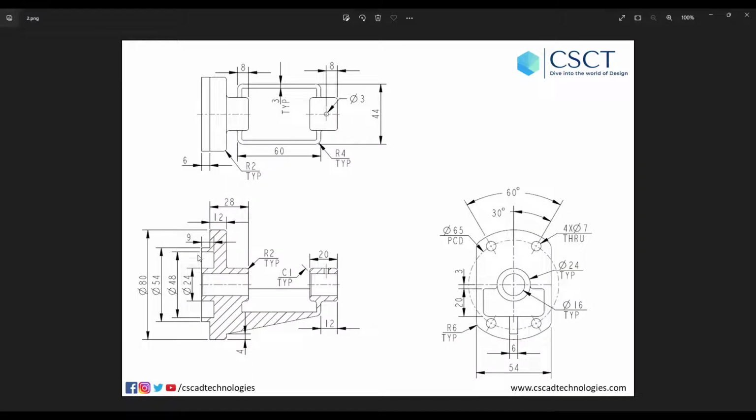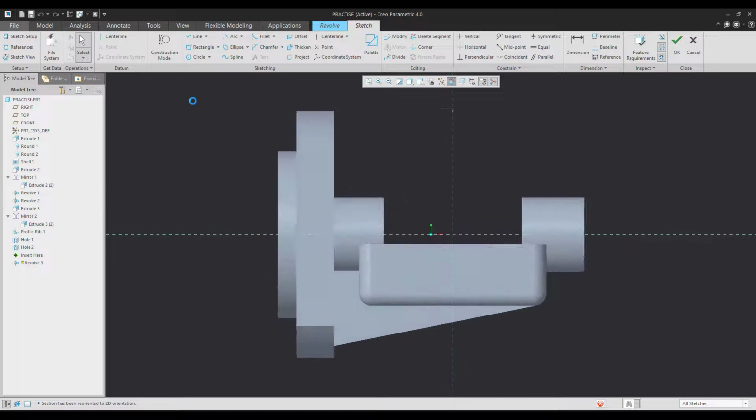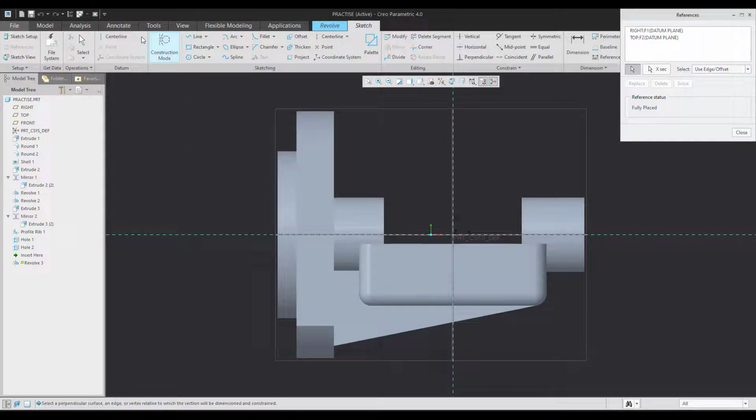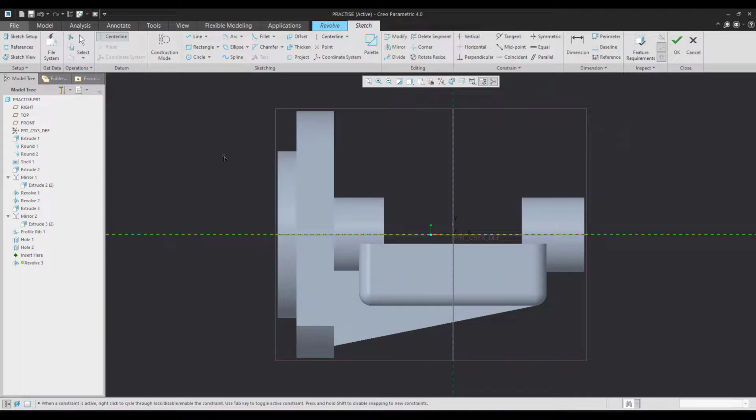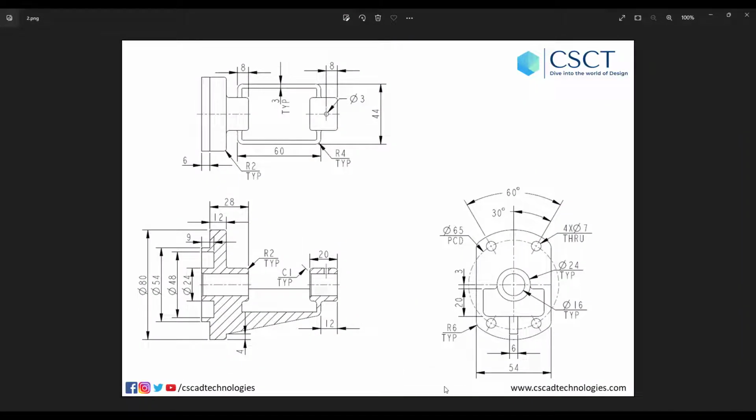There is also another feature which is a cylindrical cut, as you can see. So let me make that cut by using the same revolve command. It's easier to do it by using a revolve command. The cut is exactly at this location. Let me try to take the distances. We know this is 9 and this is 48 and this is 24.